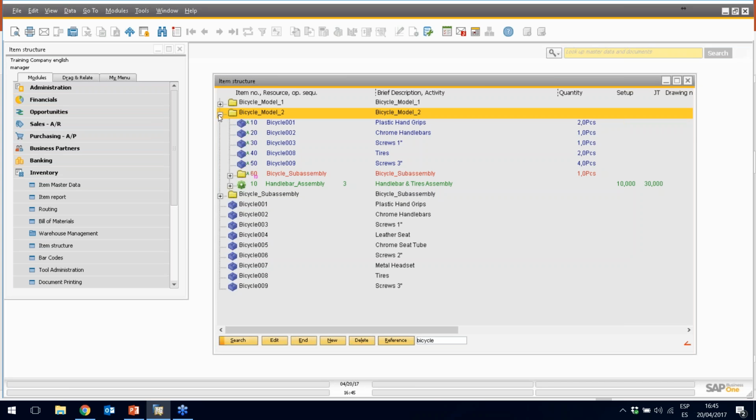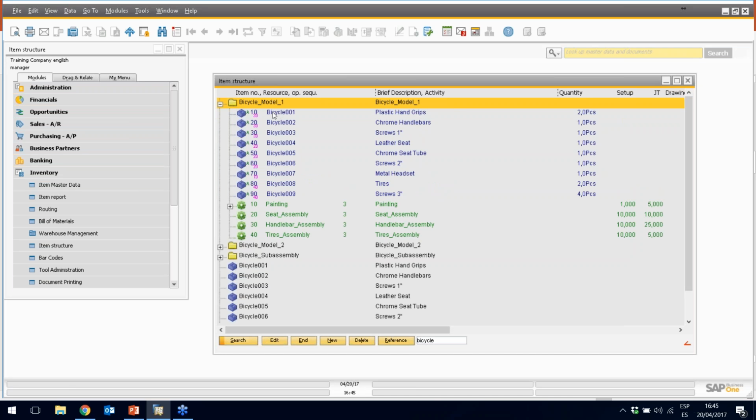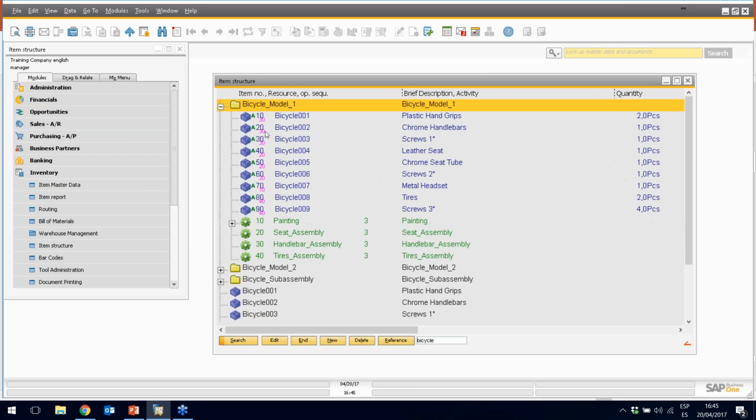So based on what we saw, okay, we can have the first scenario that is going to be the simplest one, okay, that in here you will have a bill of material, okay, we need all these parts to produce this bicycle, okay, and you will have all these tasks, okay. But what about these tiny numbers that are in here, the number 30, for example, the number 20. This means that at the moment that we are going to produce, these first three are going to be consumed on the operation number 30, the position number 30, that is about the handlebars assembly.